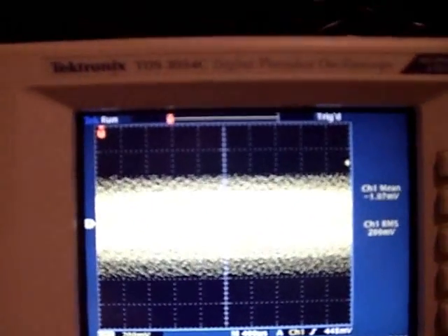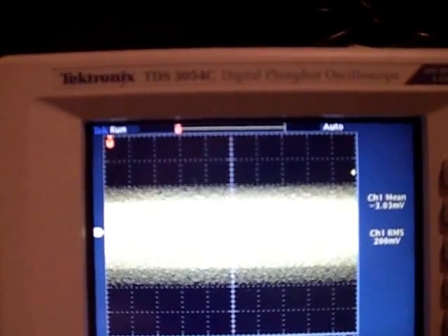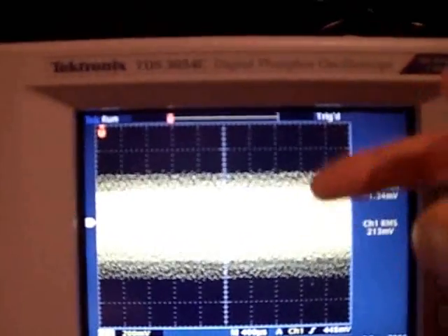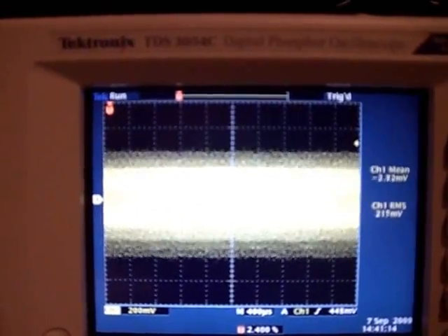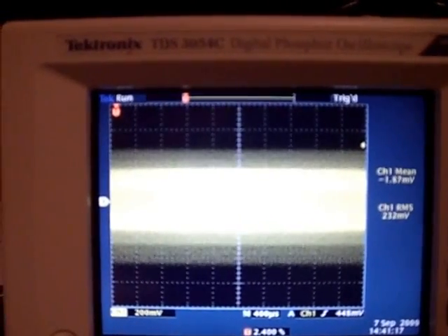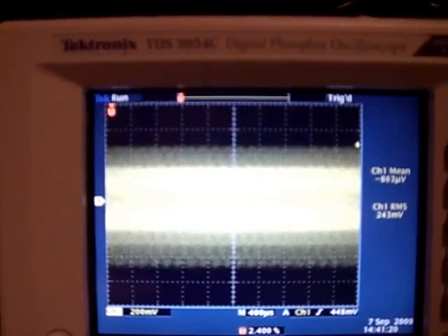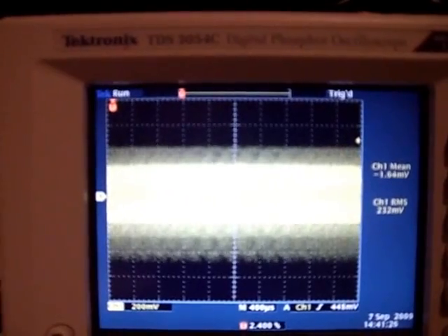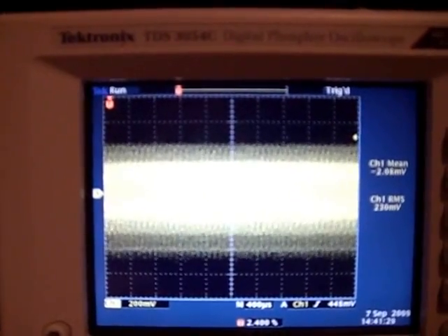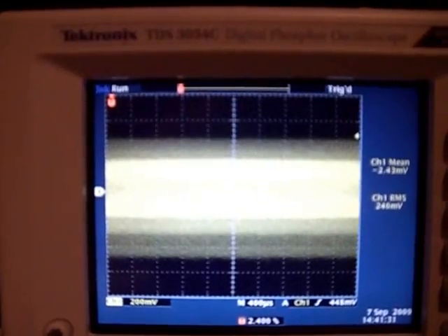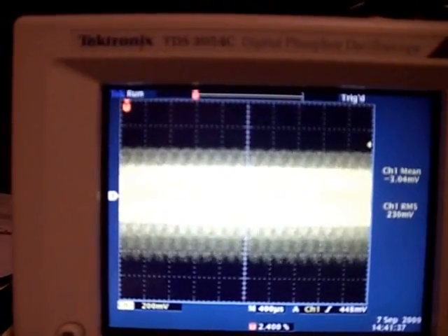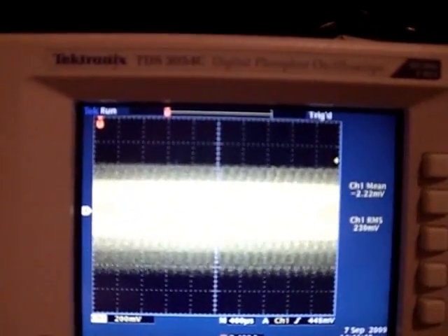I'm at maximum gate resistance, and I'm going to start decreasing gate resistance. Okay, I'm decreasing gate resistance, and you would expect the amplitude to climb, just like it is. Decreasing, it's climbing, decreasing, it's climbing, now it's starting to shrink back down. You can see that it's shrinking right there. And if I keep decreasing, now it's starting to grow again. So through this range, which I'm guessing is maybe a couple hundred to maybe 1K of resistance, it's a totally nonlinear region.